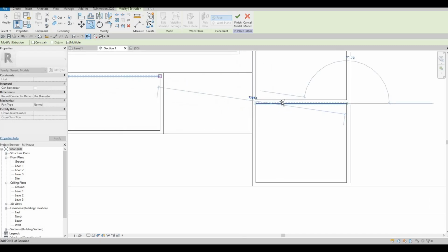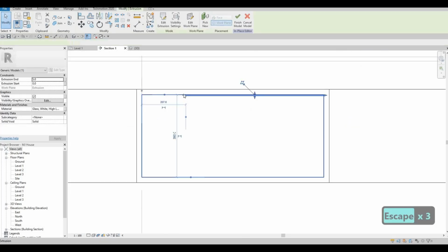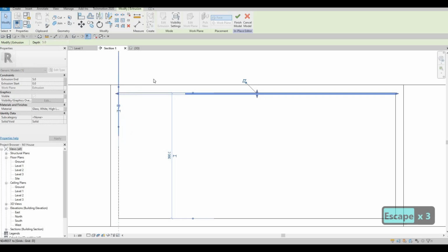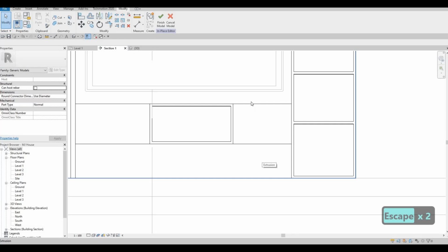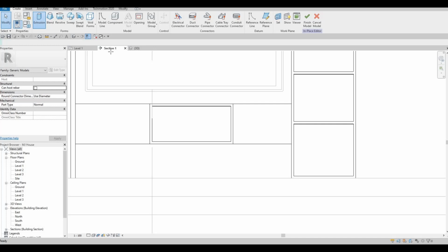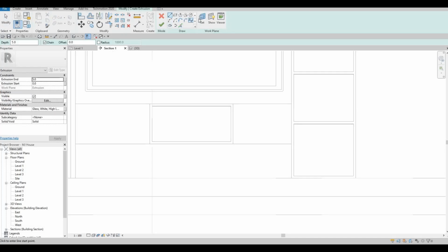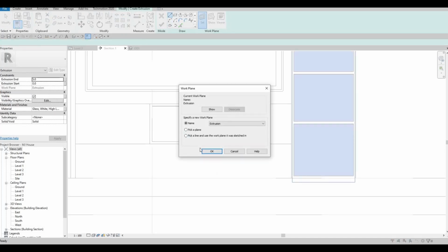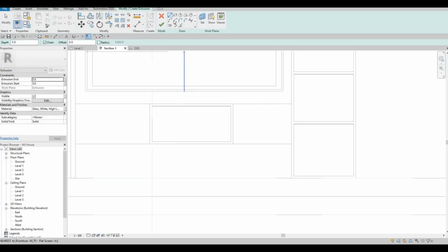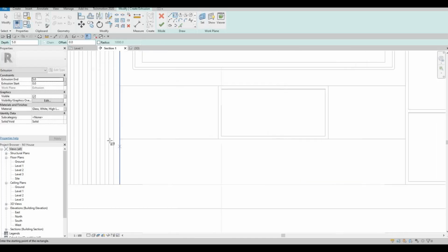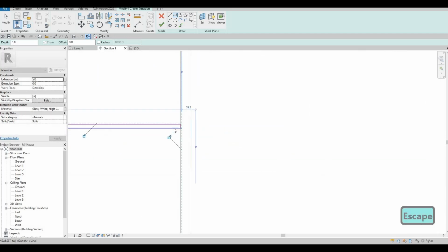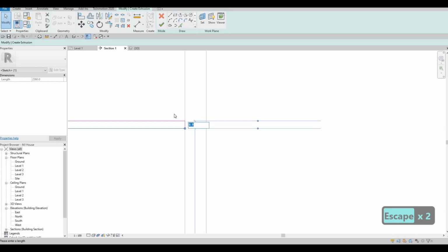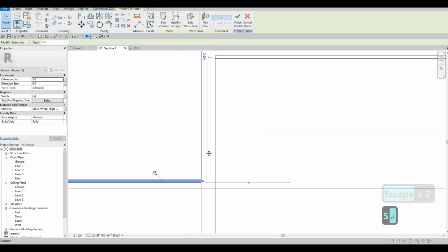This one, and then we could add it right here, and we could actually increase it more like that. And then because this back is different from this, we need to create another one. Same thing, same idea. Another extrusion. We can set this one, pick a plane, and then set this one right here now. And then here we could just create the same idea from the bottom. Select that to change it to 5, and then click finish.